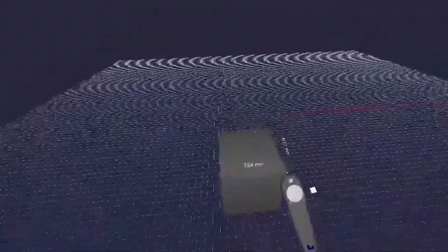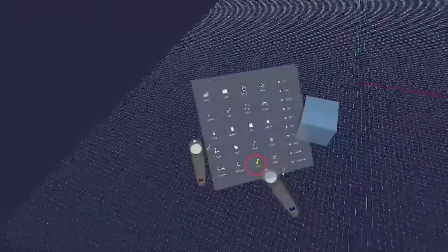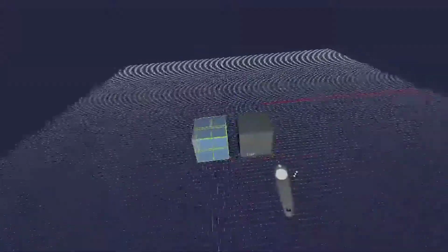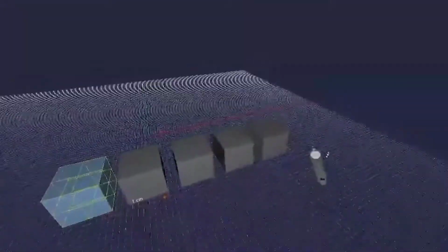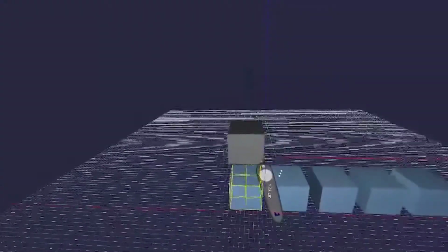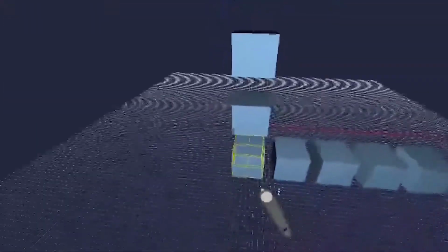I'm going to start off with making a box, and from there I'm going to use the command which is array, which allows me to copy a series of the same geometry. So first I select it, then drag using the trigger finger and holding how many pieces I would want, in this case 5. I can also do it in any direction, so in this case it would be in the Z direction, and I want to have 4. Let go when you're done with the 4th one.